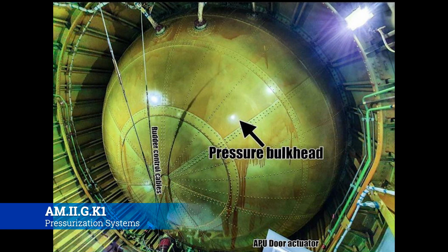Now, what does this mean for you, the technician? You have to be very, very conscious that anytime you're working on the aircraft exterior, you could potentially jeopardize this. All right. Now, you'll see in the movies that these planes will blow out an entire section of the aircraft or whatever. There's a grain of truth to that, but when you look at the engineering of the way the structure is built, it's actually made to give way in small sections, and then stop the tearing of the fuselage at different joints, and so the likelihood of you doing something that causes a massive or explosive decompression like that is fairly low.